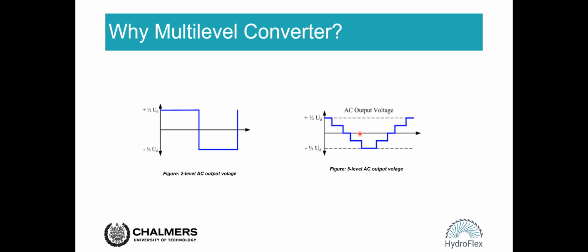But for this 5-level converter, a power switch with the capability of blocking 2.6 kilovolts is required. And that means if we go to the market, we can find more choices when selecting the switches for the 5-level converter. But on the other hand, if we add as many voltage levels as possible, then we will increase the complexity of controlling the converter. And it will be an issue to do the modulation as well if we want to achieve lower power losses inside the converter.